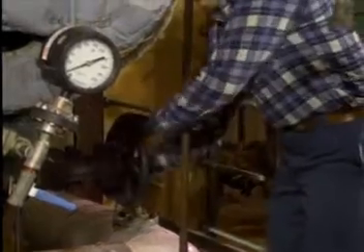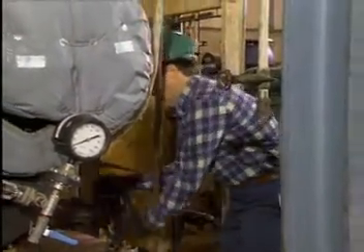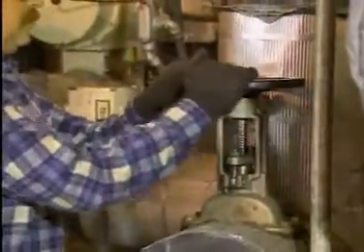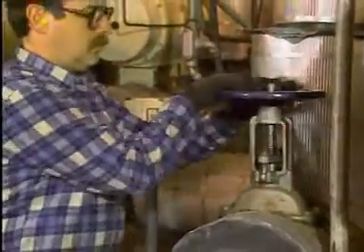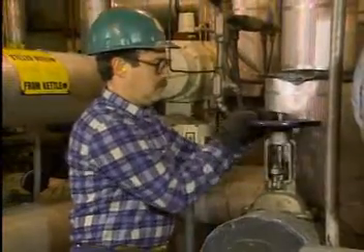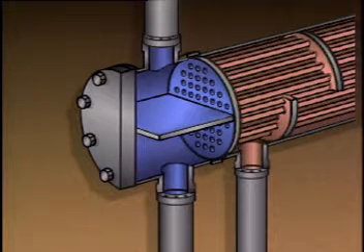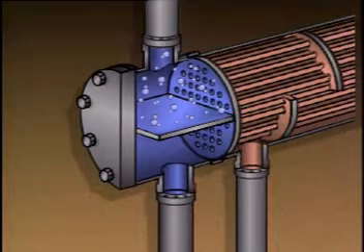There are many ways that air or other gases can get trapped inside a heat exchanger. For example, this can happen during the startup of the unit. During startup, the heat exchanger should be vented to remove unwanted gases. If the venting is not complete, gases will remain inside the unit. Another source of gases is the process itself. In some situations, the process can produce vapor bubbles. As the process fluid passes through the heat exchanger, the vapor collects inside the unit.